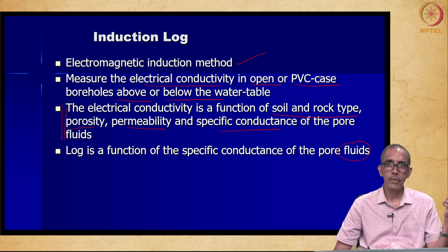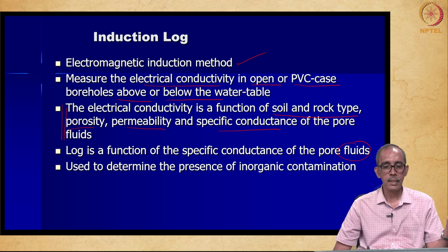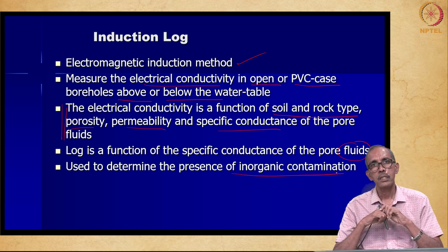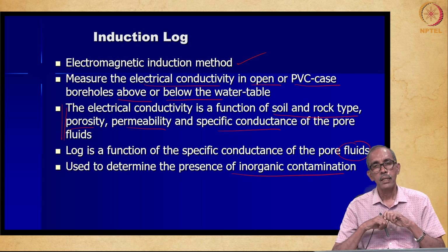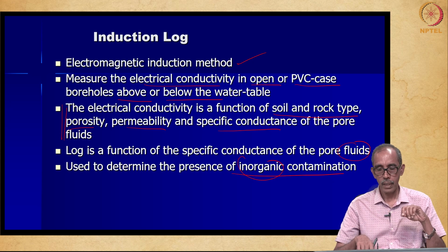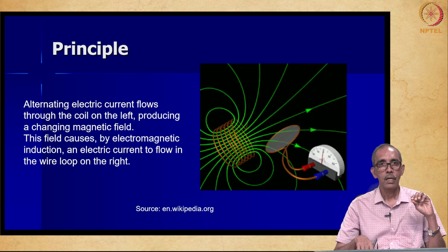Right. We had also seen previously under the electrical resistivity method that the electrical resistivity of water is less, and the electrical resistivity of oil is comparatively higher. Making use of this, we were able to discriminate in the methods we had seen previously. The same is also possible here. Then we can also use this method to understand groundwater or subsurface contamination, especially by inorganics. Inorganic contamination can also be studied using induction logging.